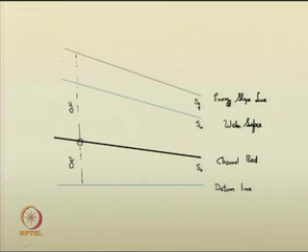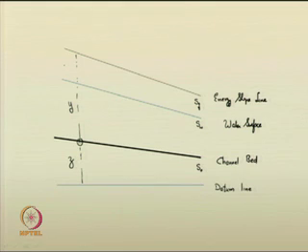As this is a non-prismatic channel, the cross sectional details come into much prominence here, and not only that, the velocity may not be uniform across the whole cross section. So, you will be taking average velocity, and therefore you may be incorporating energy correction factors and all.